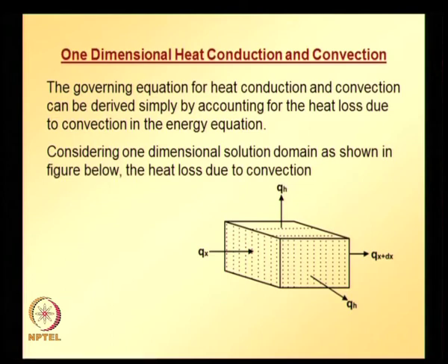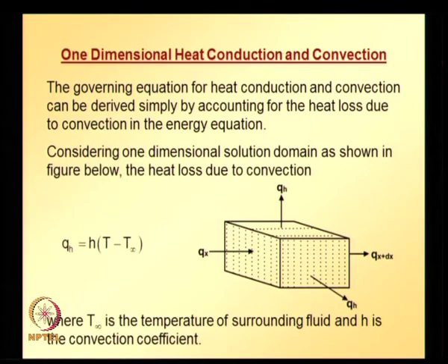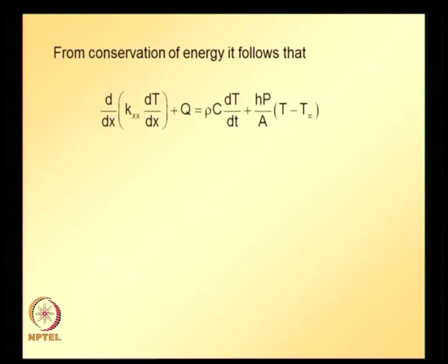Considering one dimensional solution domain as shown in figure, heat loss due to convection Q_H is equal to h times (T minus T infinity), where T infinity is temperature of surrounding fluid, h is the convection coefficient. So using this, from conservation of energy we can write this differential equation for this case, heat conduction and convection case,